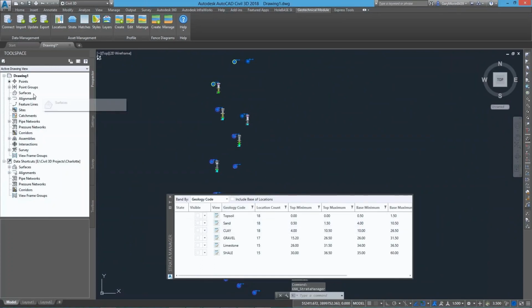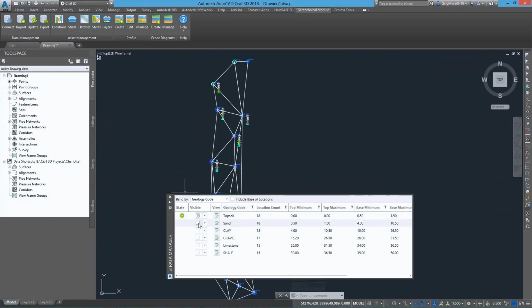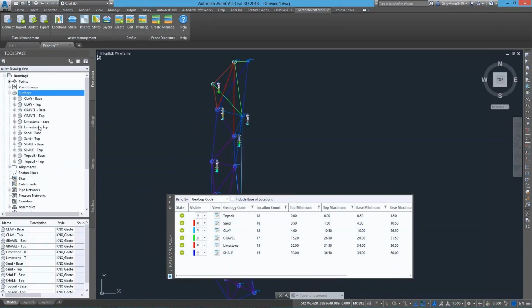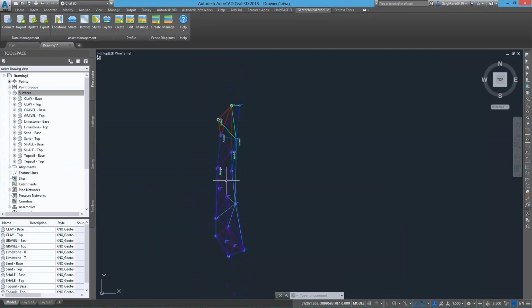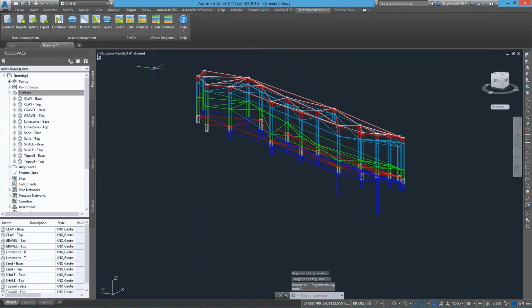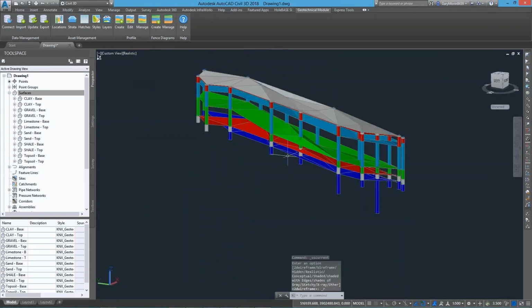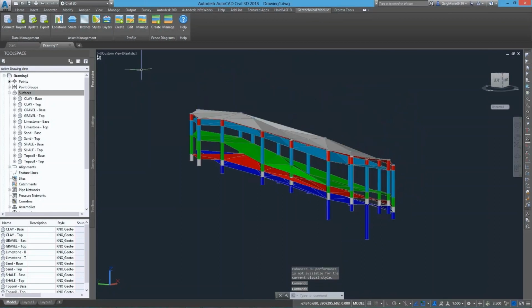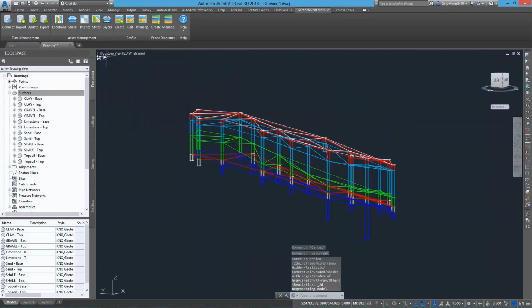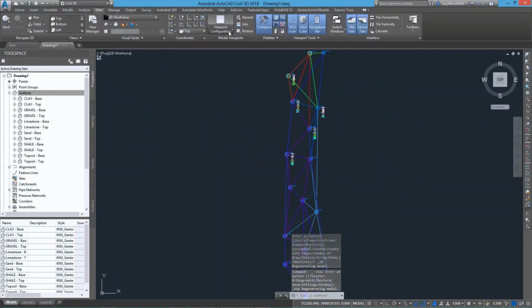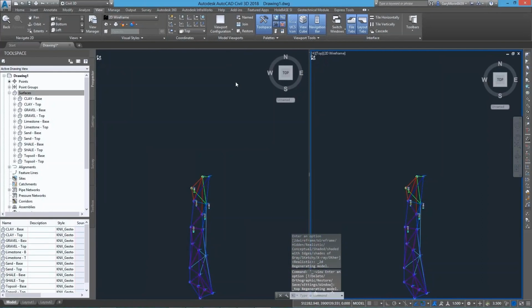I've now just gone into one of the really interesting areas of the geotechnical module, the strata manager. We've got a drawing here with no surfaces in, but in those few seconds, we've just created 12 AutoCAD Civil surfaces based on the geology, top and base surfaces for each geology material, and there we have it. Now, I must emphasize, this is just the starting point of modeling your geology. I've got some pretty nice clean data here. In reality, it doesn't come in that clean. You need to check, model, validate your information, verify it, and use AutoCAD Civil commands to help model it.